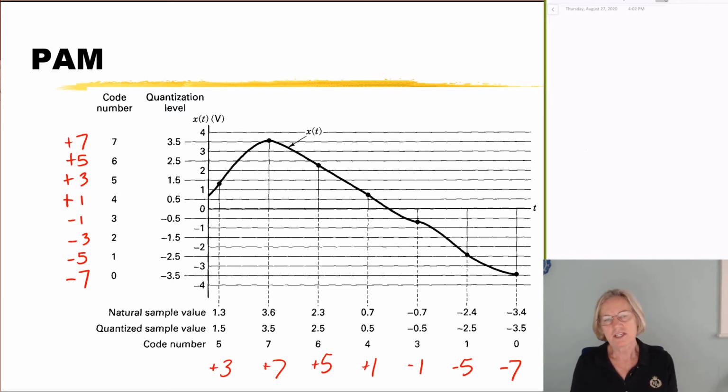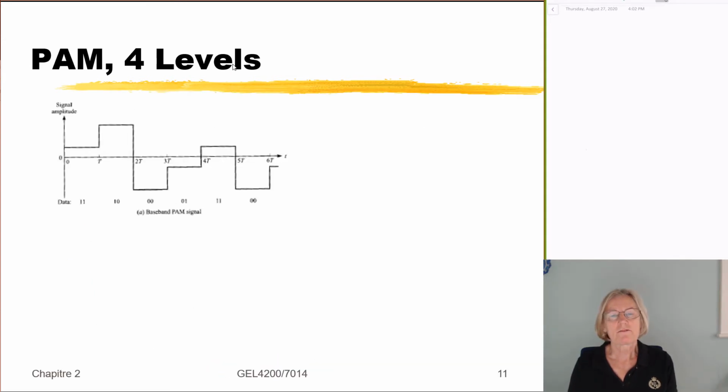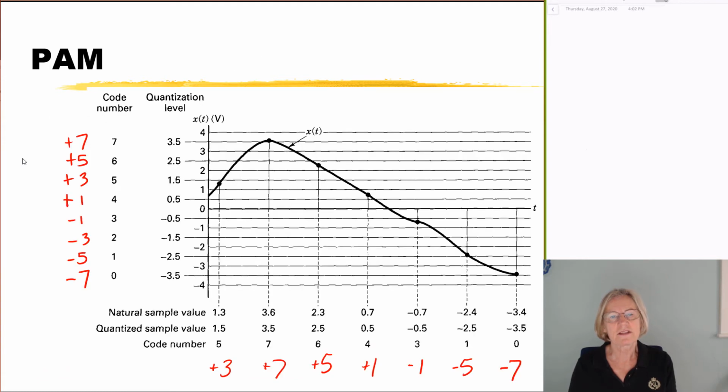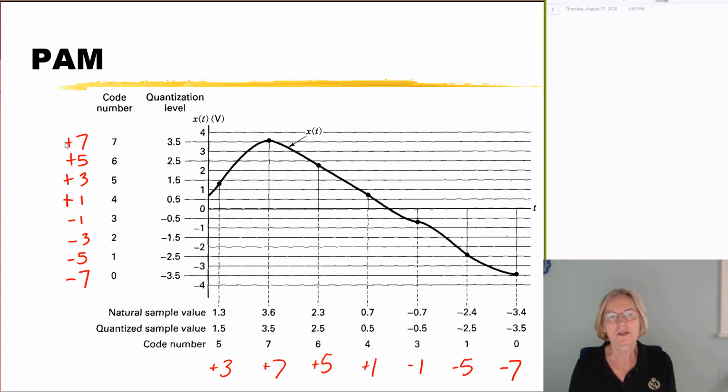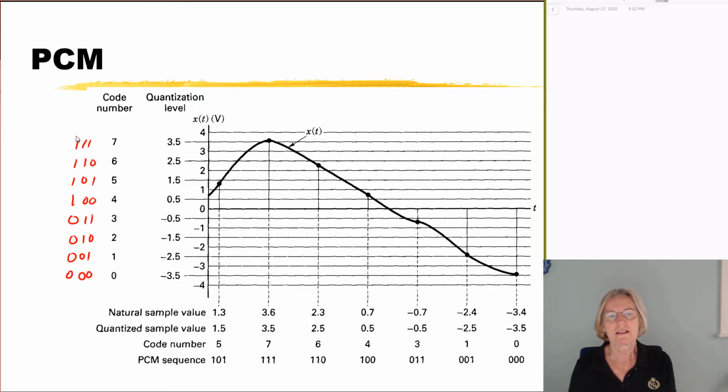And what is the implication of these 2 choices that we're looking at? In this example, we'll be looking at 4 level, and perhaps I should have been a little clearer. This is 8 levels of modulation. There's 4 absolute values, but of course there's 8 distinct levels which are going to be transmitted, and those 8 distinct levels are equivalent to this 3-bit representation. So I could send a symbol which is at plus 7, or a symbol at minus 3, or I could send 3 bits in a row, 1, 1, 1, which is telling me that the level is +7 or etc.